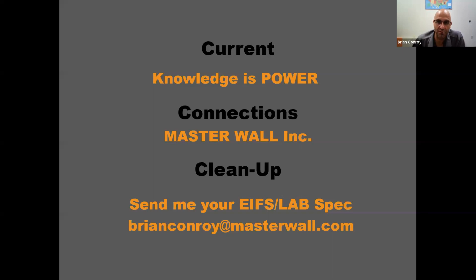The XPS group is always going to say it doesn't soak any moisture into the system. Honestly, I think there is really no advantage on either side, except to say that if enough moisture gets in to be soaked up by an EPS to the point that it causes damage, there are more problems than the EPS gaining that moisture, if that makes sense.